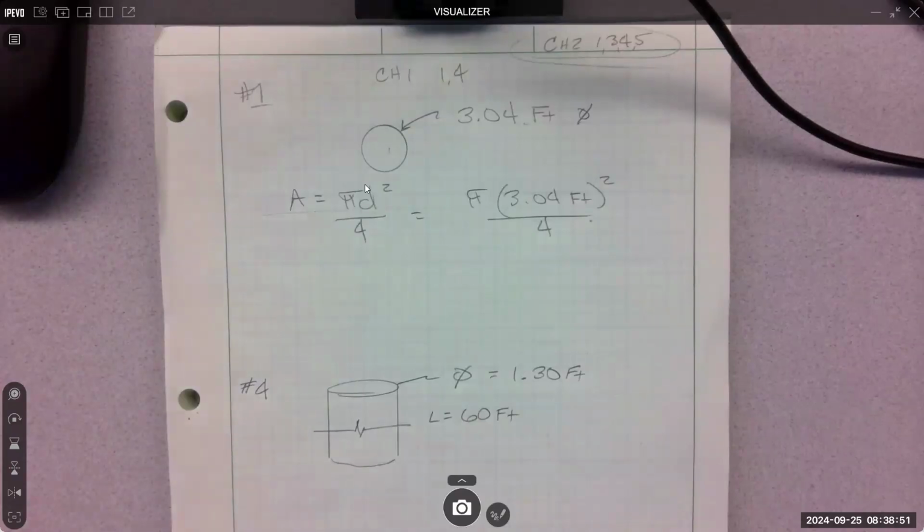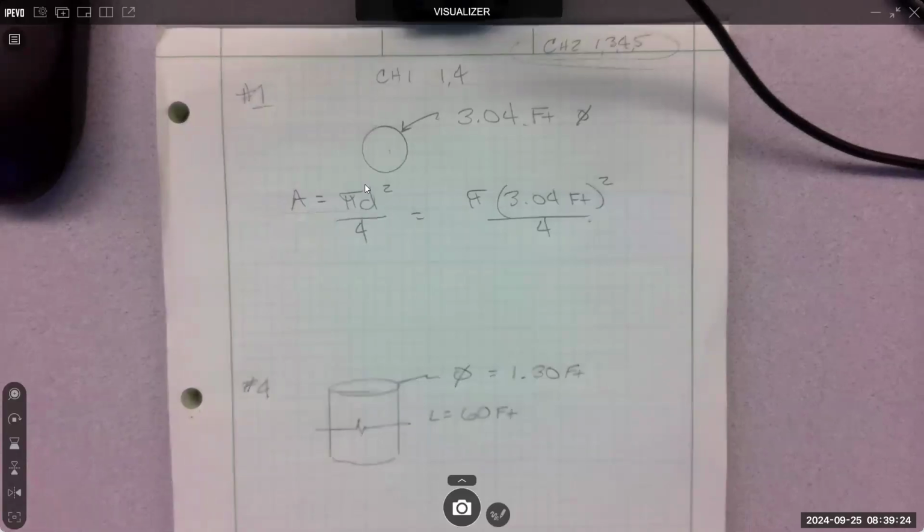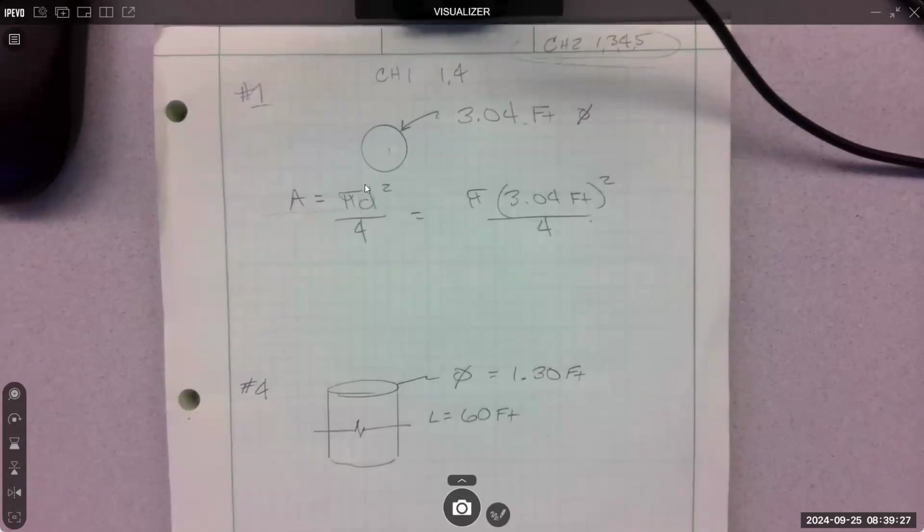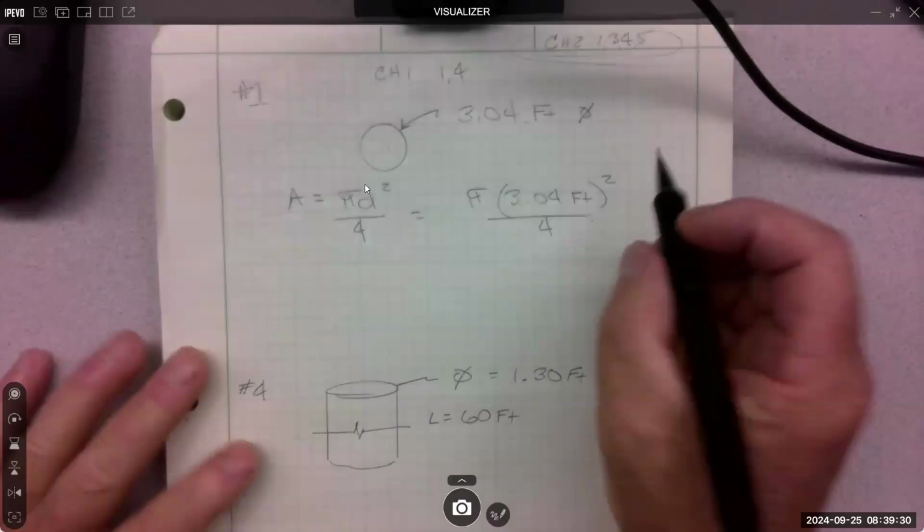We're going to get enough formulas that you're going to have to choose, like, oh, I'm running Bernoulli's equation. Bernoulli's equation has friction in it, has velocity, has head, has potentially another friction value, right? And it has those 4 terms on each side of the equation with the equal sign between, because it's called conservation of energy. Energy into the system, energy out of the system has to be equal, right? Then you can cross out some of these because we don't need them. And if you don't write that formula down, I don't know what you crossed out, what you didn't cross out, all that kind of stuff. So it's important. All right, so what did we get?